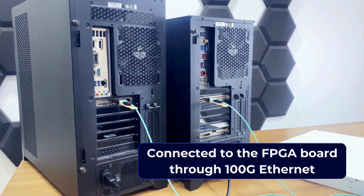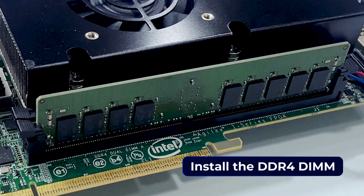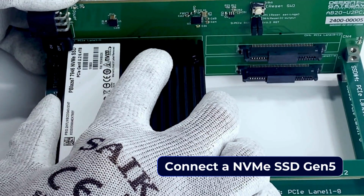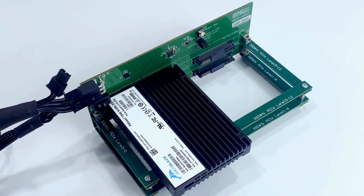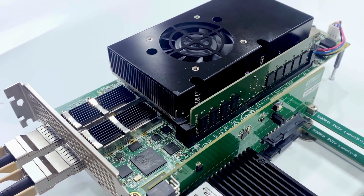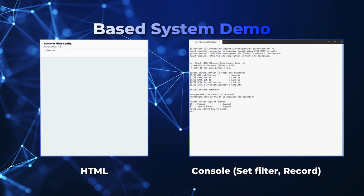First, we set up the base system. We use 2 PCs connected to the FPGA board through 100G Ethernet. Next, we install the DDR4 DIMM to provide the required buffering memory. Finally, we connect an NVMe SSD Gen5 to the PCIe interface using our AB20 adapter board. If you want to replicate this setup, we also provide a step-by-step setup guide, so users can follow the process easily. At the beginning of the demo, we need to configure the packet filter.